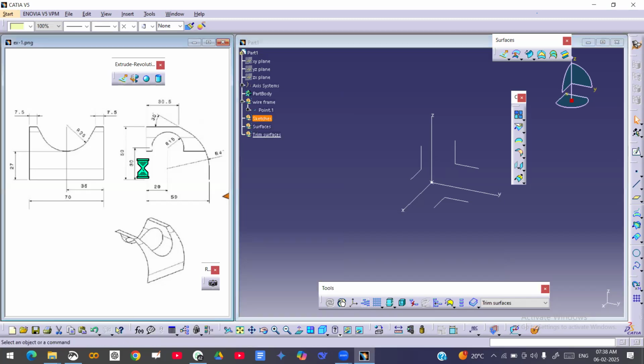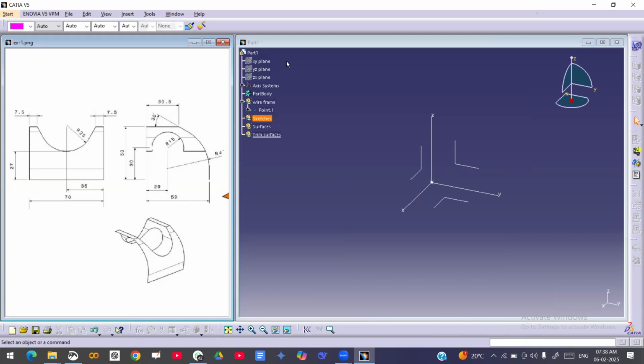Now we will do this drawing. In order to do this drawing, as I said, always you need to check the profiles, mainly the inclined lines and arcs, on which profiles this comes. You should take that only. So here if you observe this figure, here is an inclined line, this is an arc, which are lying on right and left plane. On this plane it is coming, which are parallel to right and left plane.